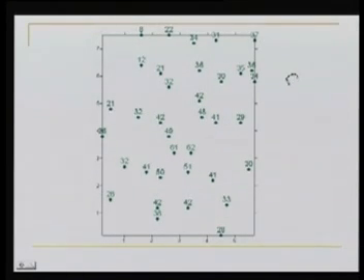Let us say our aim is to generate a contour of 60 meter, where the contour should be. If you look at this data, we have 2 points, 61 and 62. Then everywhere outside, we have the points which are lower in elevation. So it appears like we have a hill where we have 61, 62, 2 points. Then over here, we have the points of 49, 50. So this is a place like this, a hilltop.